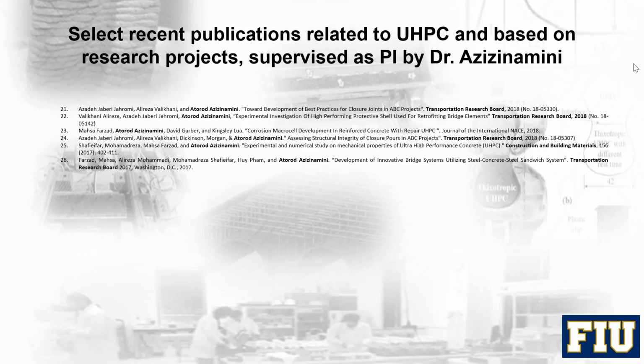Okay. Another one that came in earlier was, is pumping UHPC possible for repair cases in confined space? You had that one where you were doing it in the culvert. That was pretty confined. Yeah, I can tell you that for the shotcrete, we are pumping the concrete and then spraying it with air, and it works. And we looked at the dispersion of the fibers.